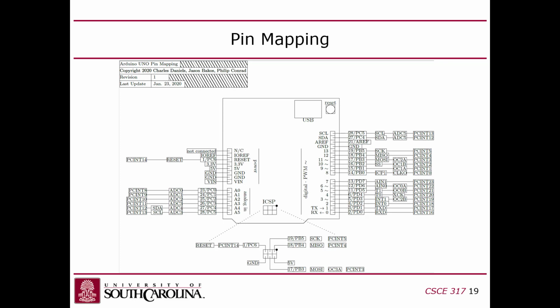But with hardware PWM, you use the software just to configure the hardware, and then it takes over and works concurrently. It will drive the PWM in parallel, so you don't have to use time or instructions to perform the PWM or output the PWM. It goes by itself.